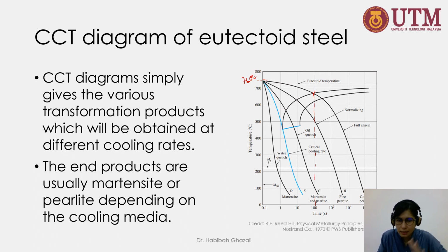And using this TTT diagram, you can predict that the transformation will begin after 100 seconds and the transformation will end after, say, around 500 seconds. So that's how you use the TTT diagram.